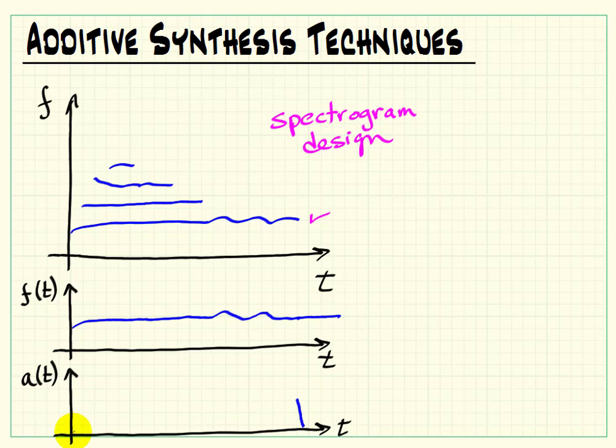And my recommendation is that you always have the frequency remain at some non-zero value, and then you use the amplitude to indicate when that partial begins and when the partial ends. If you actually set the frequency to zero itself, that can cause various types of discontinuities in your sinusoidal oscillator results that give some undesirable effects.